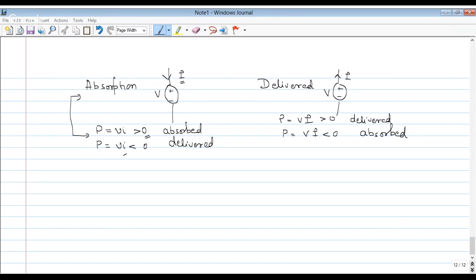I have created a machine so that the orientation of winding remains the same. That means the coupling coefficient cannot change, which means the ratio of mutual to total flux will remain the same, and the ratio of leakage to total flux should also remain the same. If you increase the current, that is, if you increase the total flux, the leakage and the mutual flux should change accordingly.